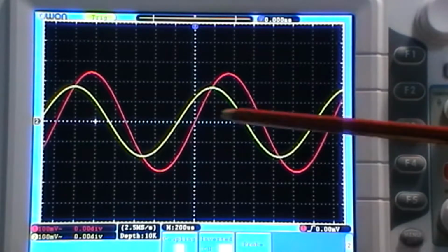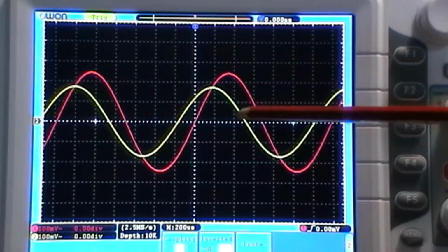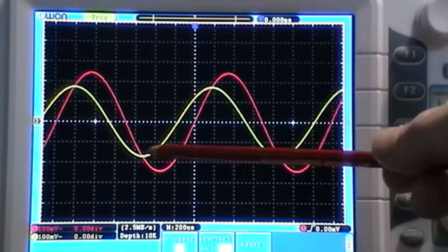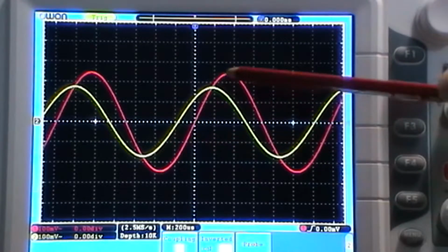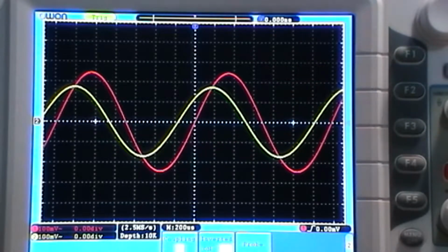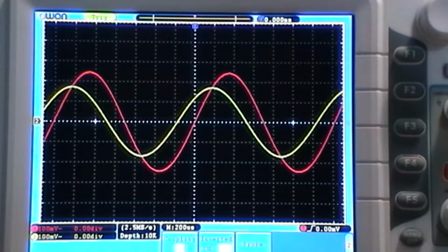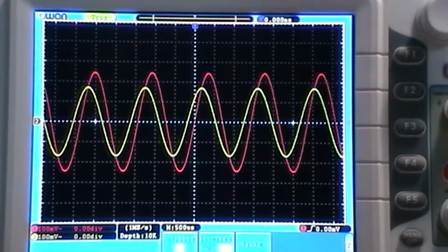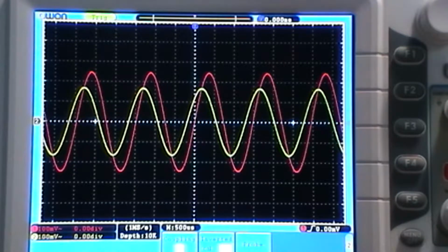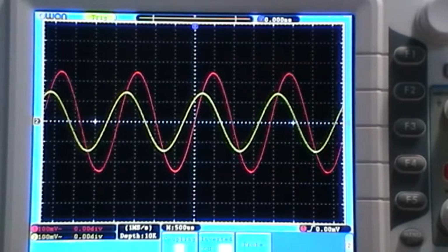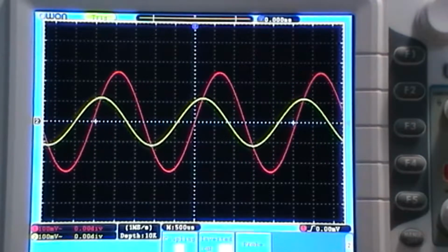And again, that looks very much like the last signal, but that time I had a 1 microfarad and we were down at 159 Hertz, and now we're at 723, and we've got basically the same minus 3 dB loss on that signal. But if I turn that signal down, let me get more on the screen there. I'm just slowly turning this signal down, and it is decreasing. Let's turn that down a bit quicker. There we go. So below the frequency, I'm losing the signal.